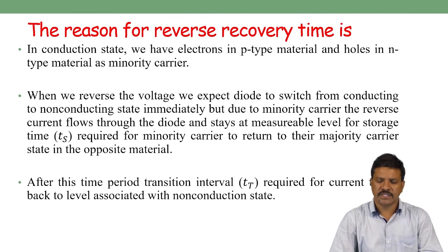The reason for reverse recovery time is all that we have studied now. When we reverse the voltage, we expect the diode to switch from conducting to non-conducting state immediately, but due to minority carriers, the reverse current flows through the diode and stays at a measurable level for the storage time required for minority carriers to return back to their majority carrier state in the opposite material.